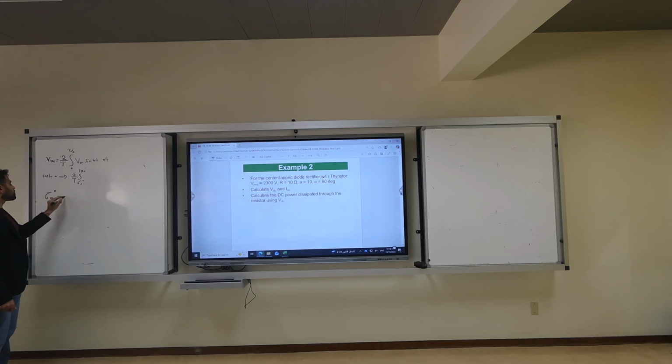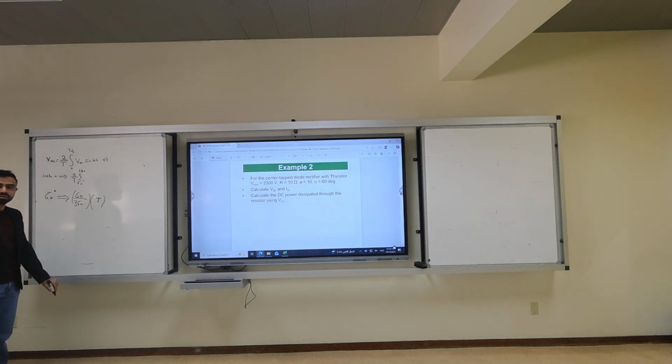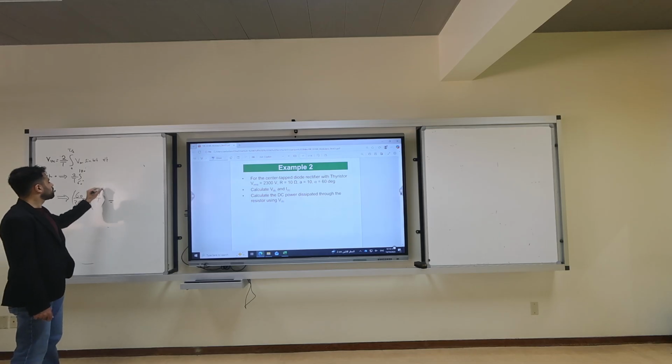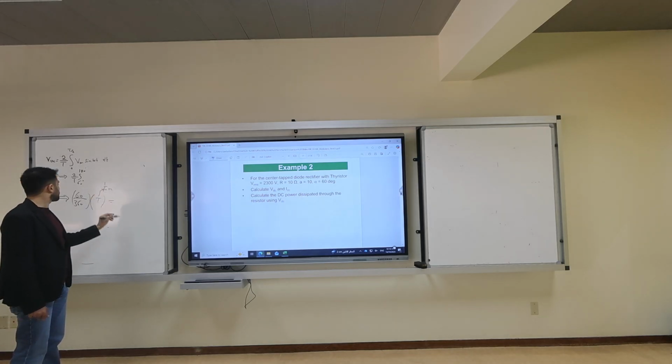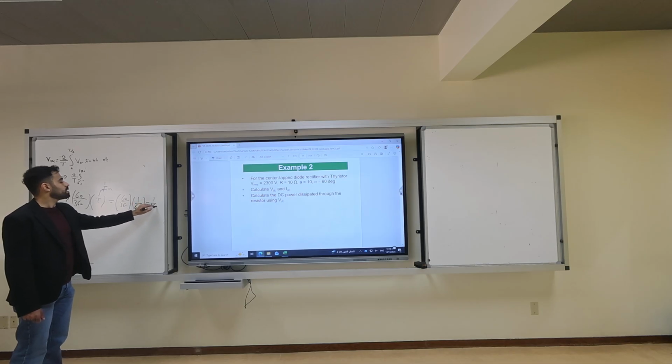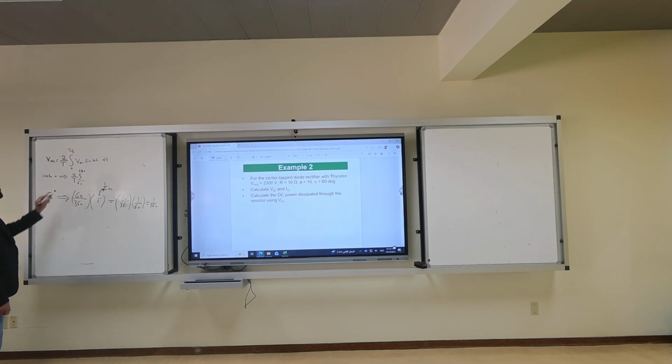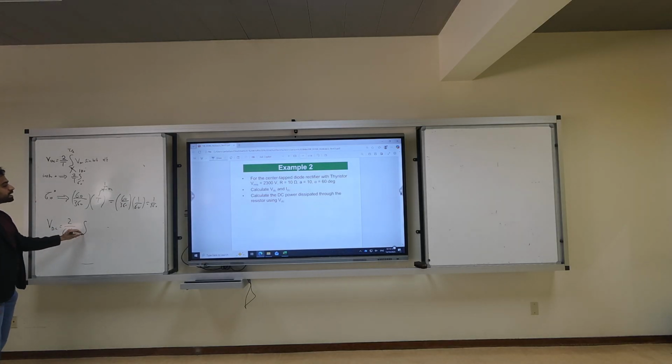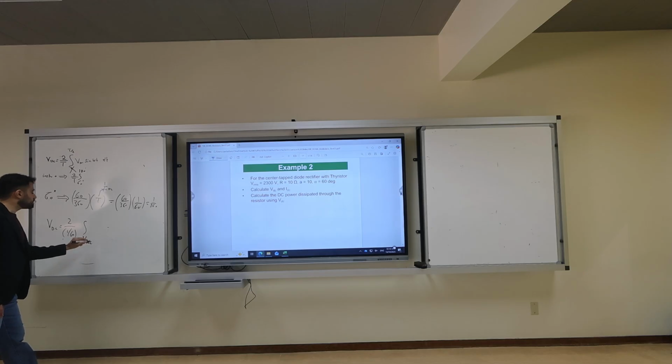So 60 degrees corresponds to 60 over 360 times the time period. What is the time period? 1 over 60 hertz. 60 over 360 divided by 60 is 1 over 360. So we integrate from 1 over 360 to 1 over 120.